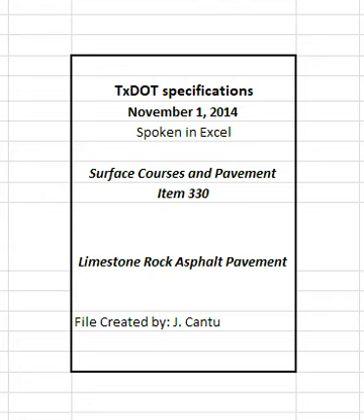Follow the selected rolling pattern unless changes that affect compaction occur in the mixture or placement conditions. Establish a new rolling pattern when such changes occur. Compact the pavement to the cross-section of the finished paving mixture meeting the requirements of the plans and specifications.